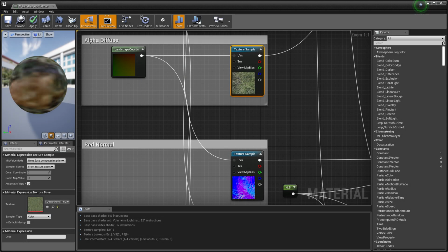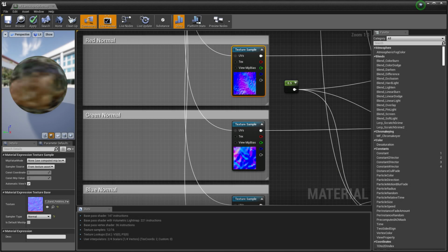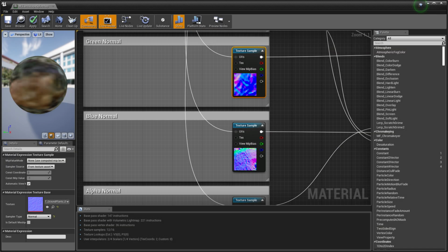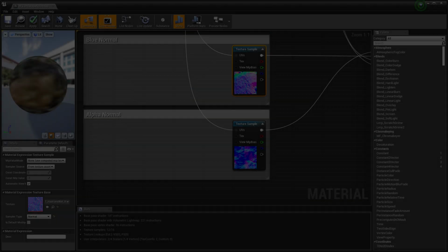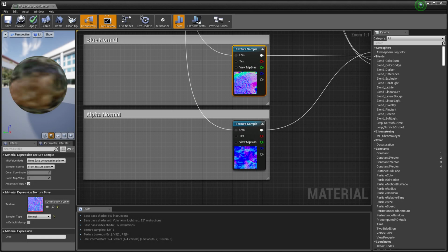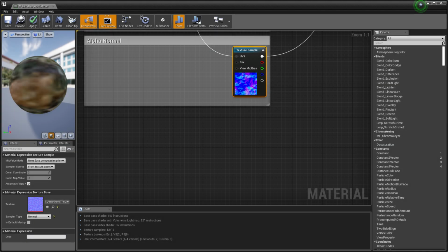The RGBA texture samples cascade through 3 height lerps with the splat map channels used for the lerp height texture input. The lerp A and B are the texture sample or cascaded lerp from the previous lerp set, and the lerp transition is a constant with the value 0.5. I have also preset the material's metallic, specular, and roughness to constant values. Click on Save to save this material.